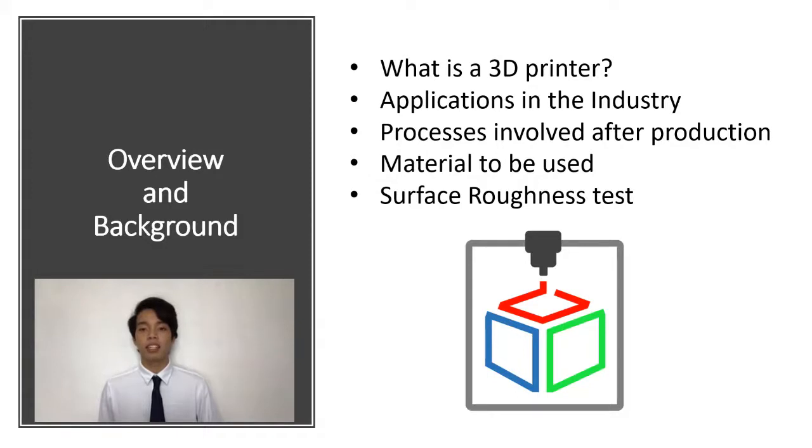In this project, the researchers used ABS filaments. ABS filaments are mainly used for prototyping, especially in engineering, due to their high strength and resistance to heat and impact. The surface roughness measurement test was done on the outside part of the specimen. In this study, the researchers used a contact-type device for surface roughness measuring, which was the SurfTest SJ210. It can measure an arithmetic average of the roughness profile and the arithmetic mean width of the profile elements.